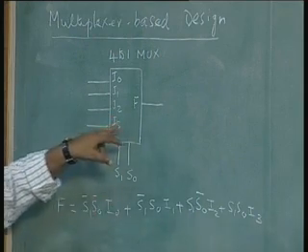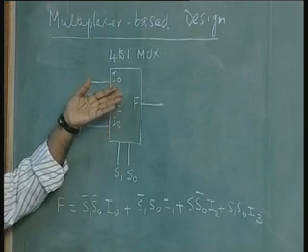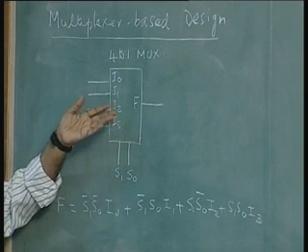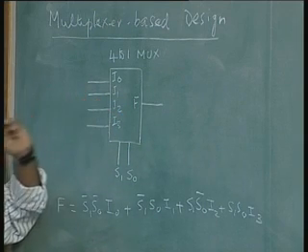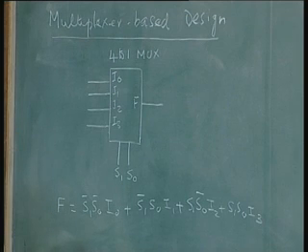If you break into the multiplexer and see what is inside, you still will find AND gates and OR gates. Like any other combinational logic, everything can be reduced to a basic set of AND, OR, inverters or a universal gate.